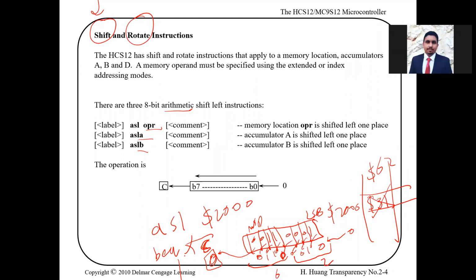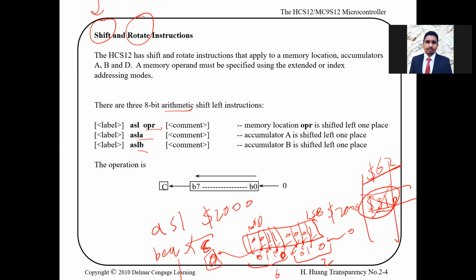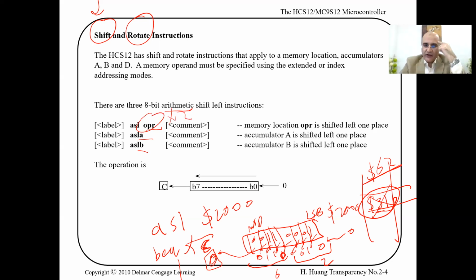They call it an arithmetic shift, because a shift left is basically in math a multiply by 2, right? So the number that was here was 31. After shifting it left one time, the result is 62. So we multiplied this operand by 2, right? Every shift left will do a multiply by 2. If you shift left twice, you multiply by 2, then by 2, so you multiply by 4, right? And this is really much faster. If you check how many clock cycles the arithmetic shift left takes from the CPU, compare it with the multiply instruction, you'll see that the multiply is larger.